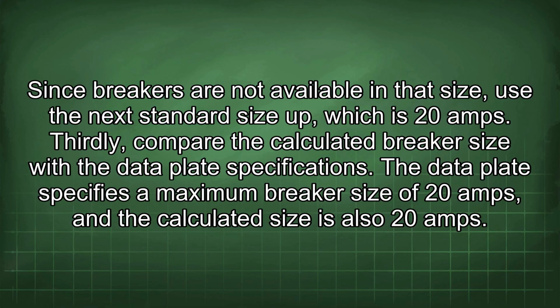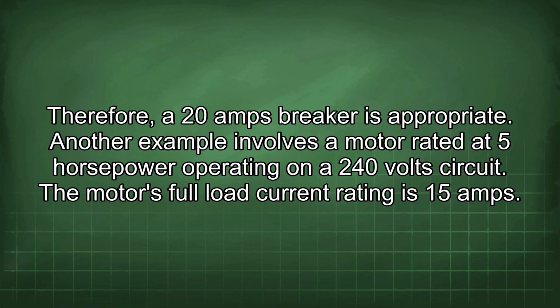Thirdly, compare the calculated breaker size with the data plate specifications. The data plate specifies a maximum breaker size of 20 amps, and the calculated size is also 20 amps. Therefore, a 20 amp breaker is appropriate.